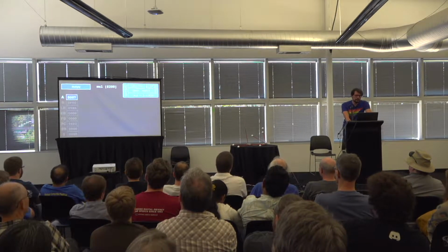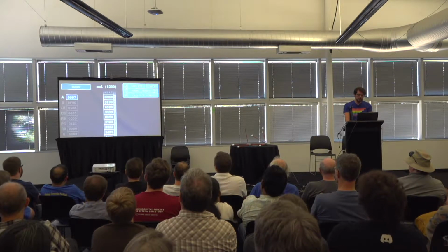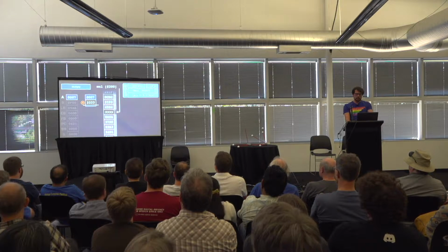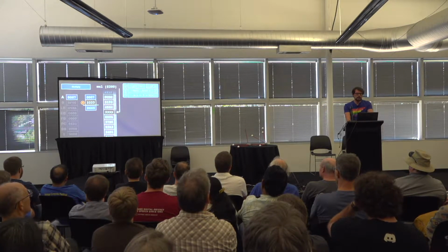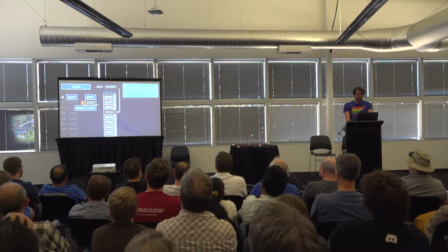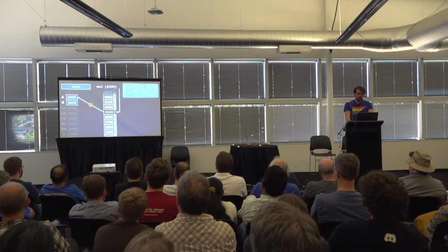Optimized for scientific calculations, the CPU has dedicated multiplication circuitry. The mul instruction reads a word from memory and multiplies it with the accumulator. When you multiply two signed 15-bit words, you'll need up to 29 bits. That is 2 words for the result. The complete result will be written into 2 registers, the upper half into A and the lower half into B.